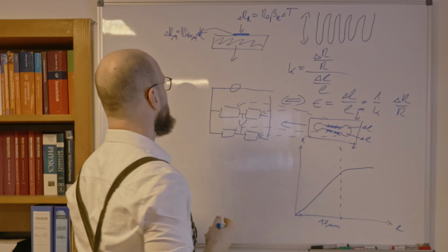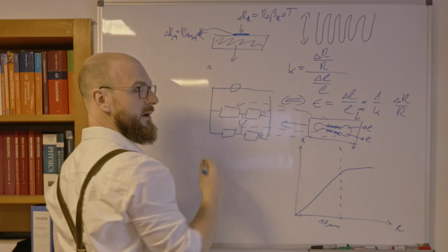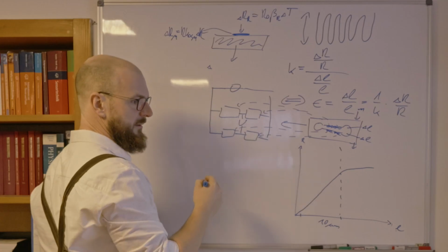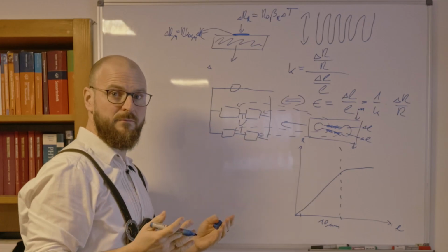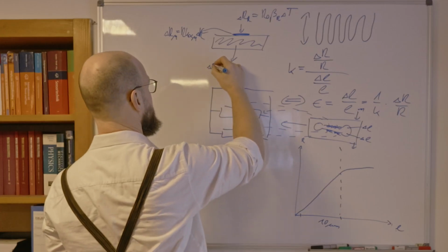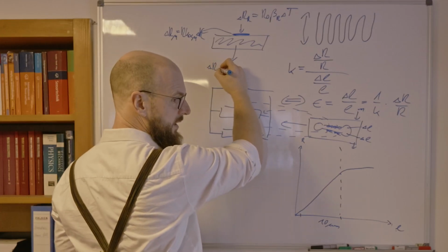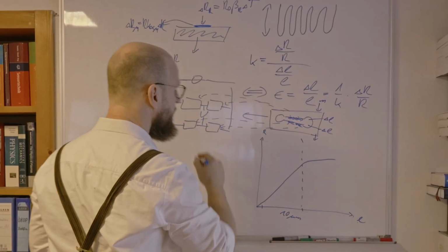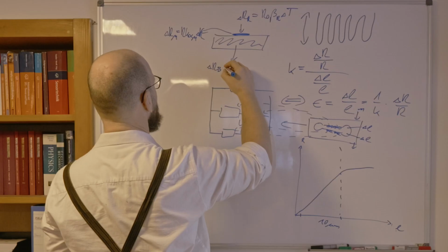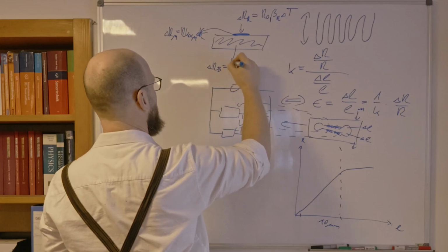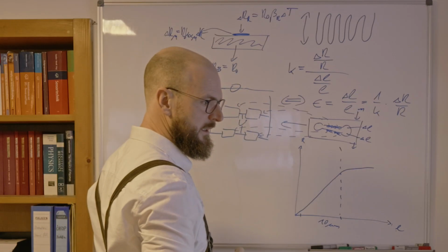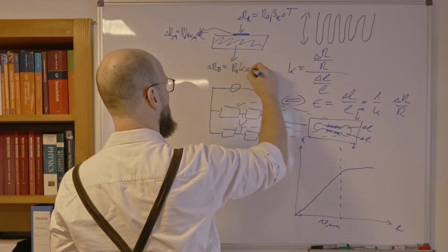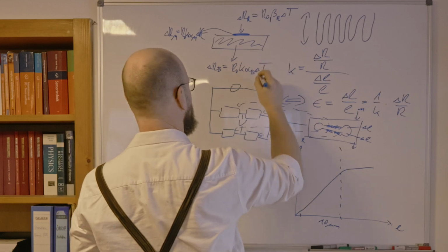Moreover, the same behavior will occur to the component, the measurement object itself. It will also enlarge with the temperature, but in a different way. So we get different constants, and let's call that the elongation due to B, delta R_B is R0, again, always it's about that R0 times K times another constant times the temperature change.